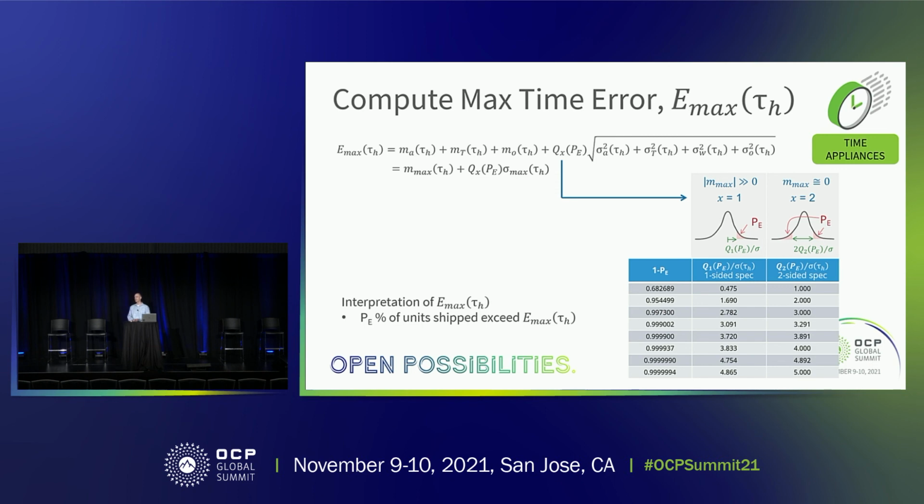So your question is, do we need to weight each of the distributions differently before we add them up? Correct. The reason is that each of those factors impacts oscillator holdover differently, so simply adding linearly may let one factor override another factor's impact on the oscillator performance. My understanding is that it does add as shown, because it's just traditional Gaussian statistics that we're adding up.